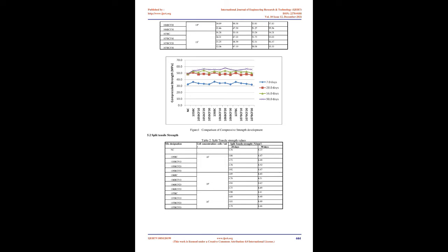Microbiologically induced calcium carbonate precipitation, MICP, is comprised of a series of biochemical reactions. In this process, an alkalophilic soil microorganism, Bacillus pasteurii, plays a key role by producing urease that hydrolyzes urea to ammonia and carbon dioxide. In aqueous environments, the overall chemical equilibrium reaction of calcite precipitation can be described as: